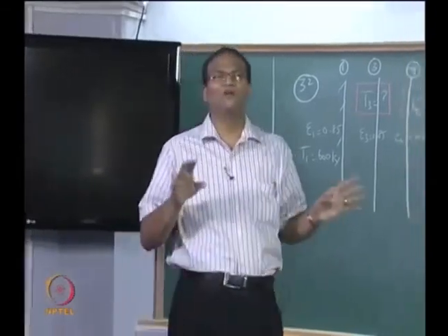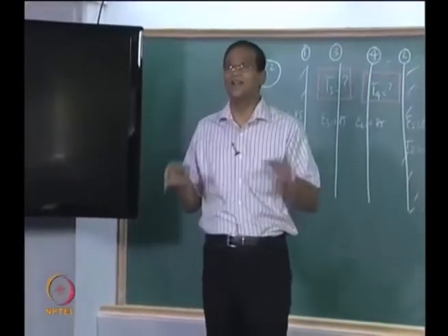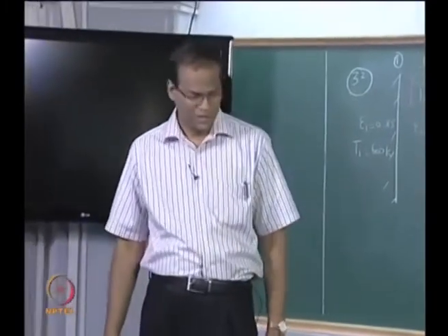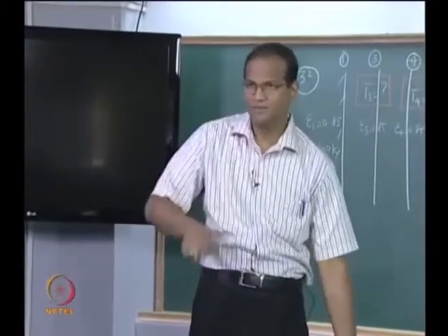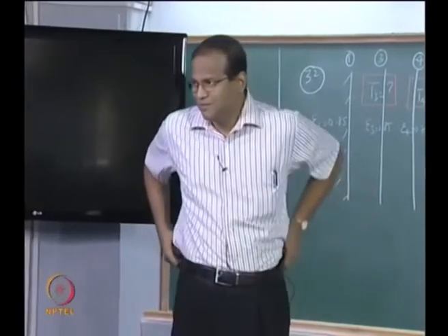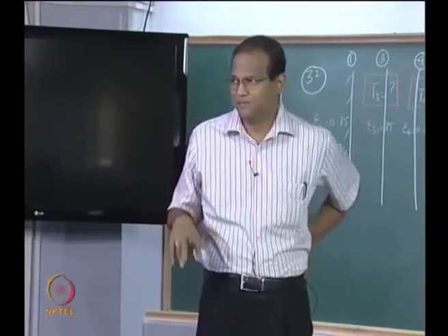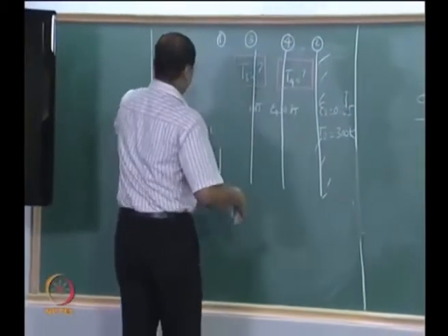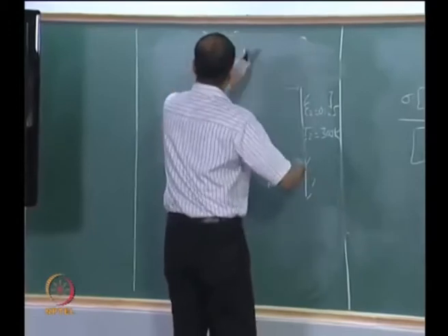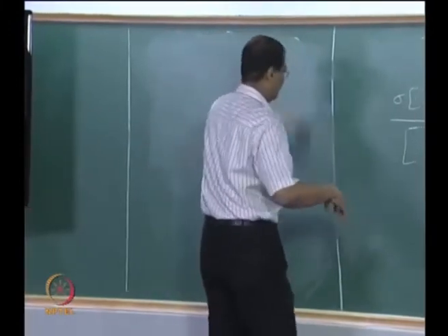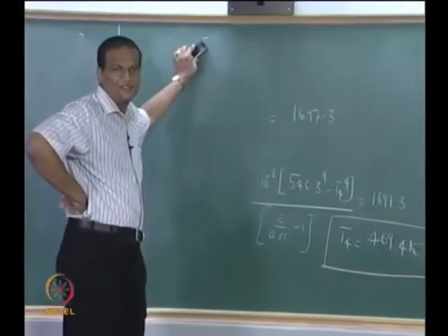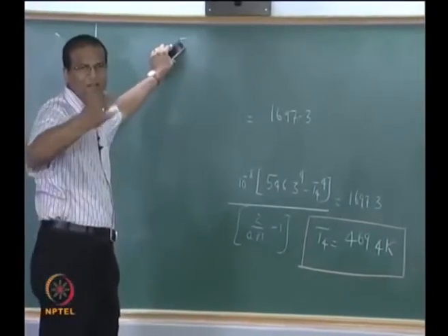So in fact the radiation shields are re-radiating surfaces. If you consider them as one body, they have only one temperature. Because they are a re-radiating surface, the temperature or radiosity must be independent of the emissivity. That is what we derived in yesterday's class, right.